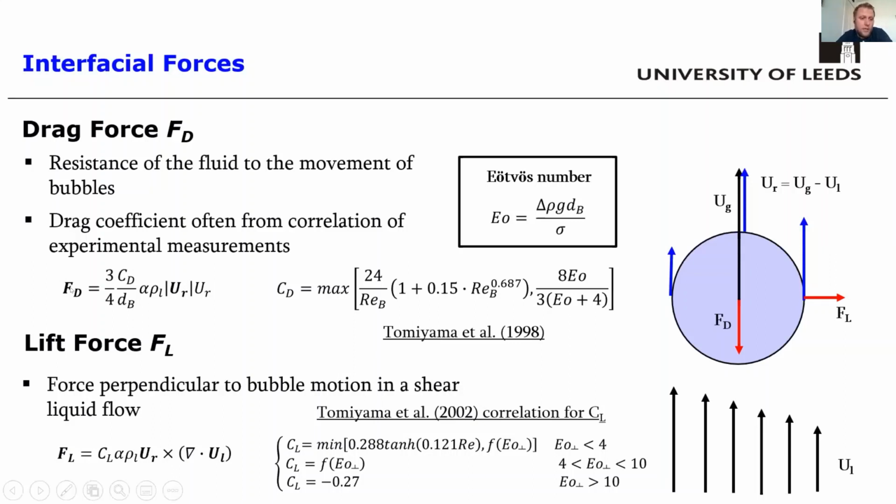You see in the equation for the drag force, and how that is modeled, in particular the drag coefficient is given by an empirical correlation function of the bubble Reynolds number and of the Eötvös number. There are different kinds of correlation, and many are the options also available in reactingEuler foam.